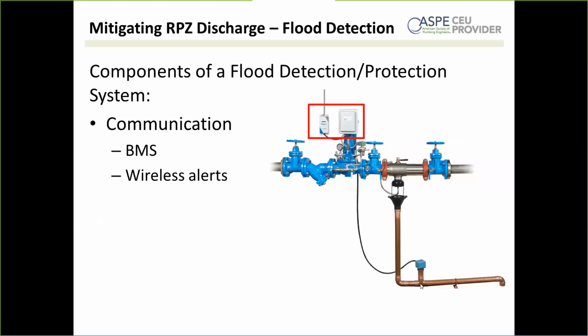Okay, what is the best way to keep checking head loss? So I think we're talking about a strainer. If you have routine maintenance, I see in a lot of buildings, maintenance personnel going around, they might be doing sub-metering on different applications to keep track of that. They have to go check the state of various parts of the system. Just taking a look at the head loss across that strainer is part of your routine maintenance, right?